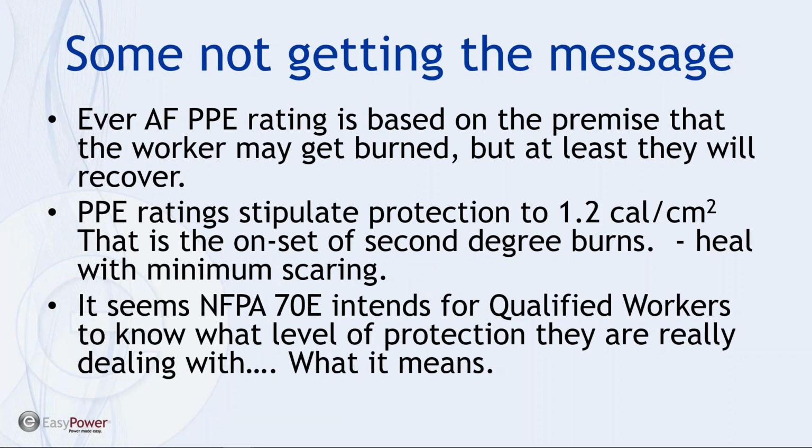The arc flash PPE rating is based on the premise that the worker may get burned, but at least they will recover. If you think about what the regulations are, the PPE ratings stipulate their protection down to, at best, 1.2 calories per square centimeter. That number is based upon the level of energy that it takes to develop second-degree burns, and that's an acceptable level of damage because at least the worker will heal with minimum scarring.